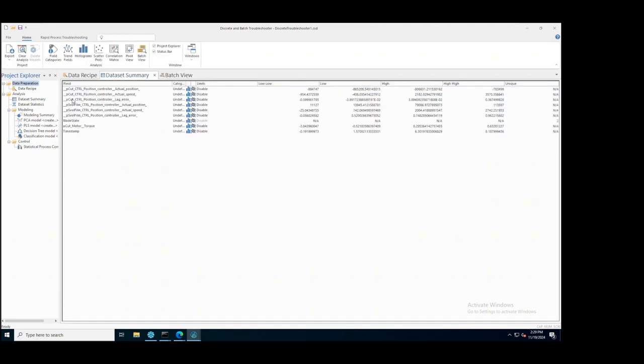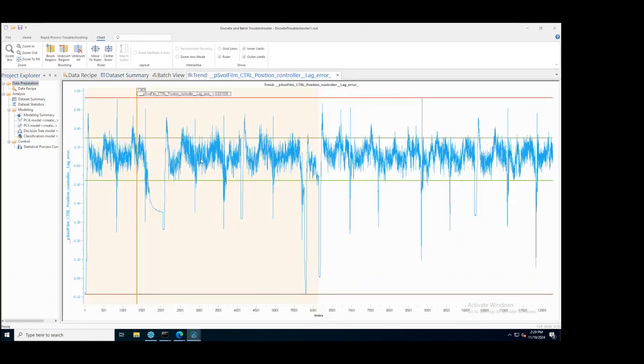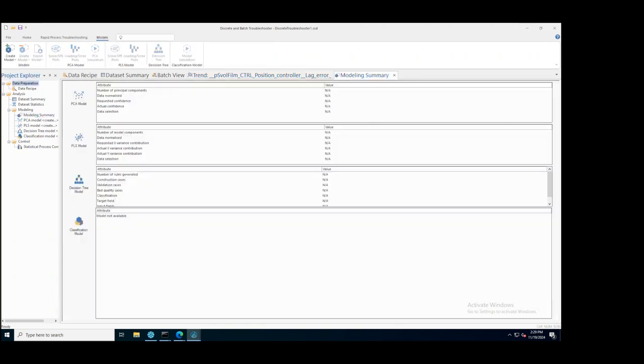This is also really nice from a visualization perspective. We can then move into the visualization and very visually see where the difference in the new and the old blade is. So once again, we can try and do this with our eye and determine what is the contributing factor between all of these tags, which will help us to determine whether a blade is new or old, and that can become especially difficult. In this case, we have some noisy data, which is not really that easy to interpret. So we will be using the principal component analysis model. All right. Principal component analysis is especially appropriate for this use case, and it is used very commonly in industry for this purpose, to try and determine whether a specific piece of equipment is degrading or behaving in an abnormal way from the way that it normally behaves.